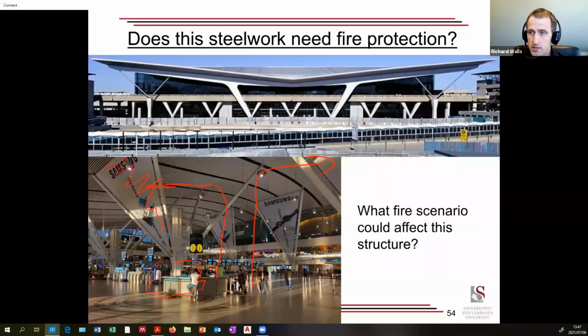But at the same time, if I was the consultant on this, I'd go belts and braces. This is a national key point with a lot of unknown scenarios. So these main load-bearing elements are not the time to go light. However, there may be staircases or light elements which, if they're being affected by fire, everyone's dead on them. And if they collapse, they're just going to fall onto the concrete slab. Those are less critical. Maybe we can look at leaving those unprotected. Or if they're part of evacuation routes, maybe we need to protect them so they have post-fire capacity.